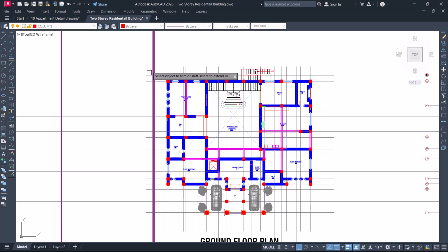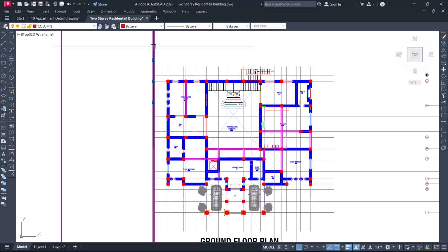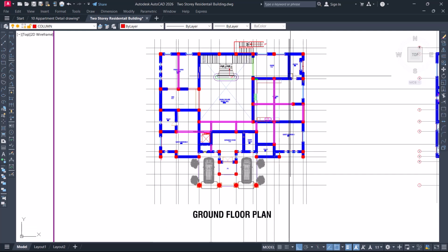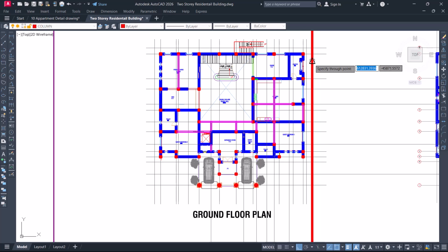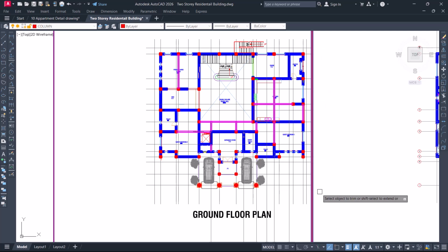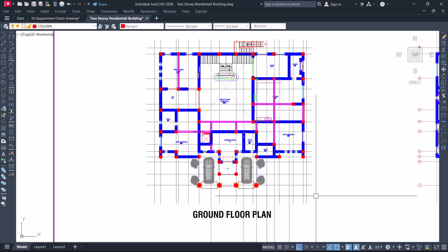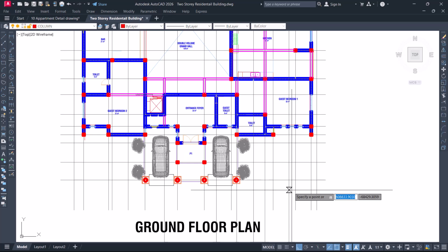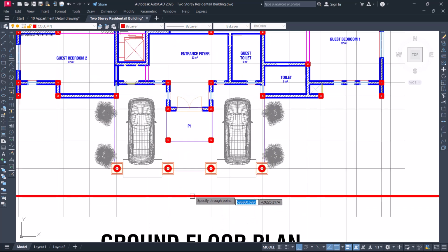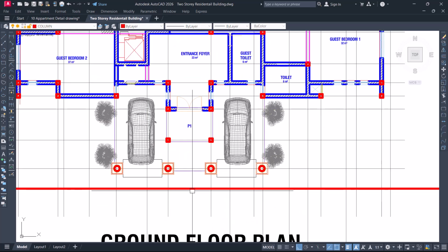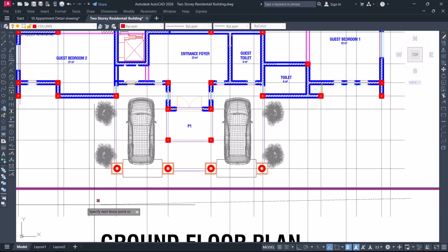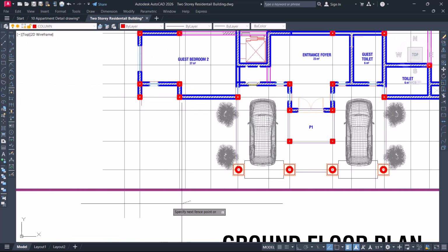Trim off these excessive ones. This goes. Again, delete this. Again, XL enter, V enter. Again, come here, trim off these excessive ones here. These grid lines, trim them off, and again, delete this. And again, XL enter, H enter, and again come here, remove this one here, and trim off the excessive ones. That's fine. Again here, that's fine. Then now you delete this.